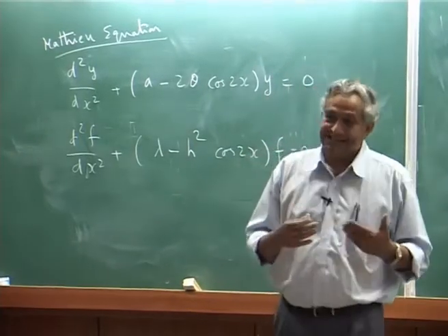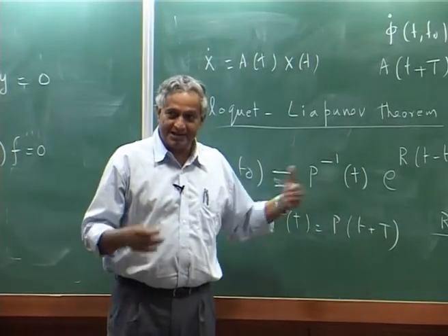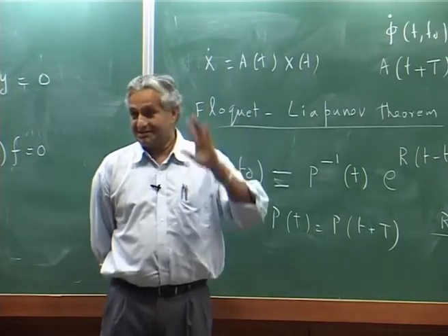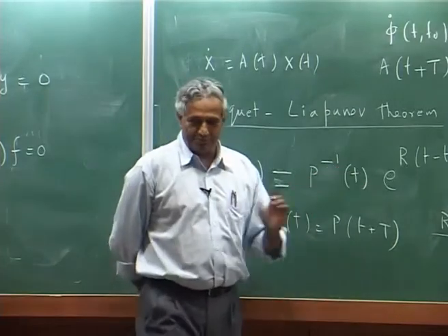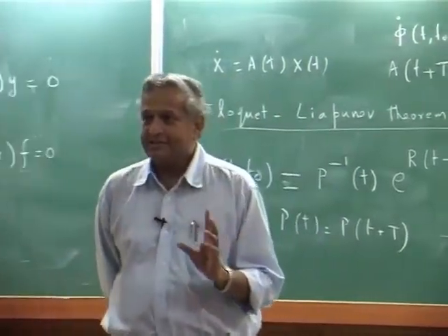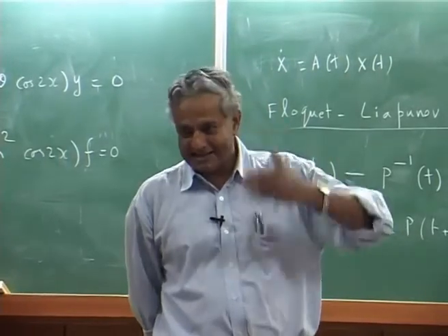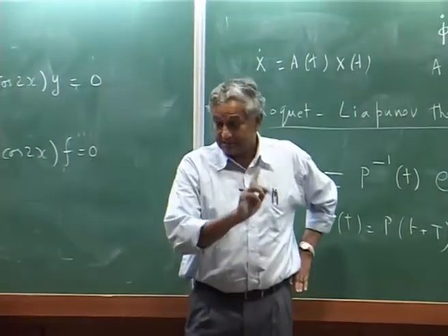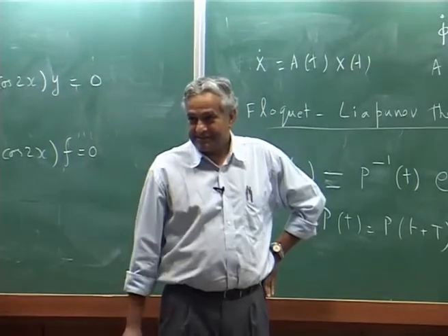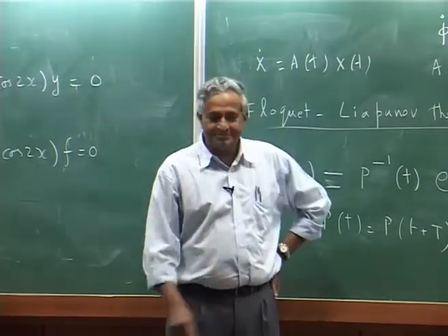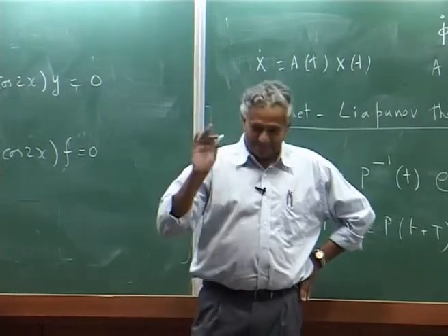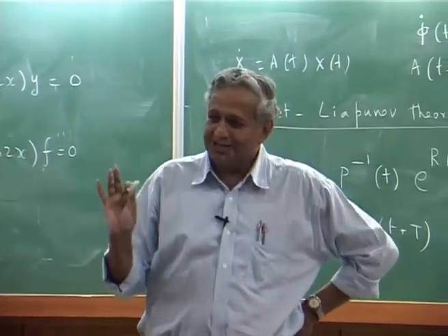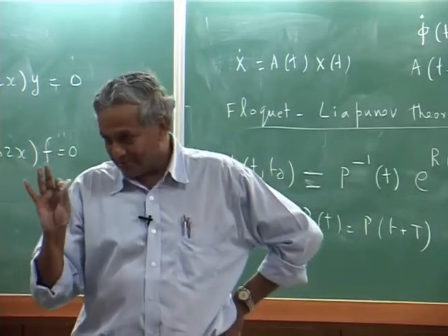So, this is the procedure that is adopted to find out the stability of the rotor blade in forward flight, not for the simple flap problem, but flap lag torsion stability. They use the Floquet theory, get the transition matrix and then the roots of that theoretically. These are all theoretical calculations. Industry, whether they use it, normally they do not bother, I will put it that way, because you try to design the system such that you do not get into any of these problems.